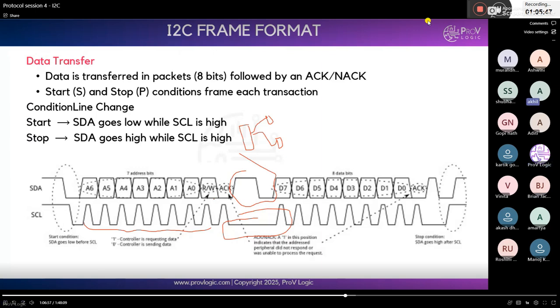So how is the clock low in between? We are controlling the clock in between. That is what we call the clock stretching concept, because here the address is on SDA and the data is passed to the slave, and the slave keeps working on the present operation.